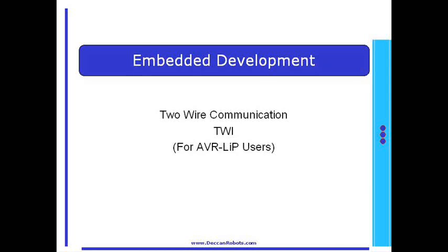But with the introduction of TWI, we require only 2 port pins of a microcontroller to do the same interfacing job, provided the device connected to it supports the TWI protocol. Let's see a graphic on the next screen.